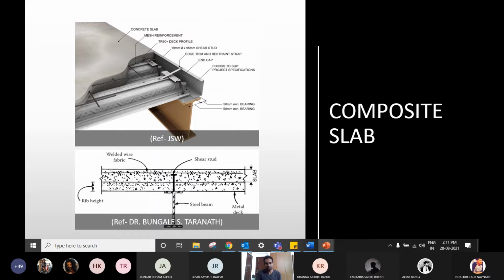You would have designed steel connections. You would have done tests, checks for the shear strength of the bolt, the bearing strength of the bolt and the plate, the tear strength of the plate, and one more thing, depending on your edge distance, or in another way, you could be giving a minimum edge distance.